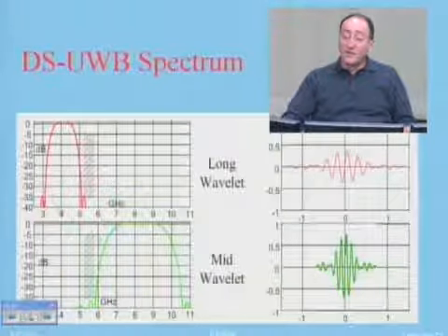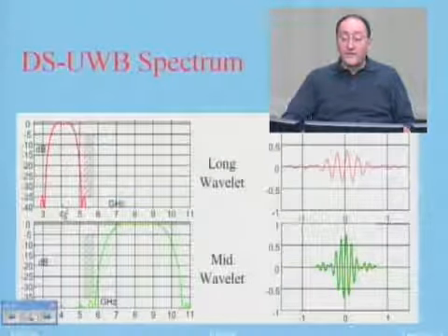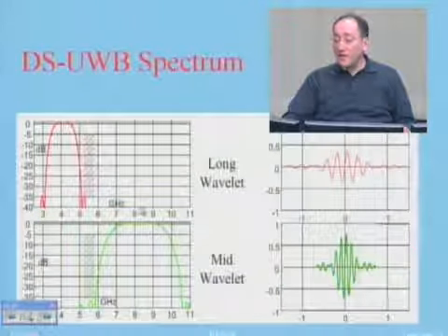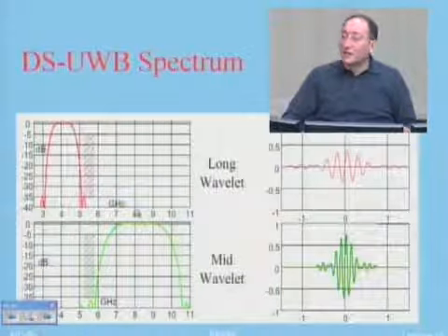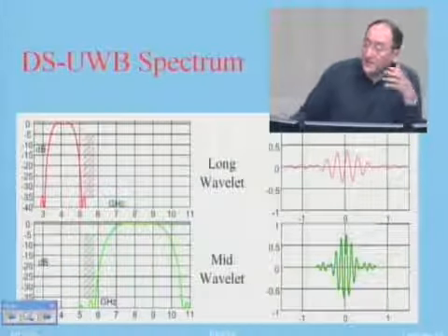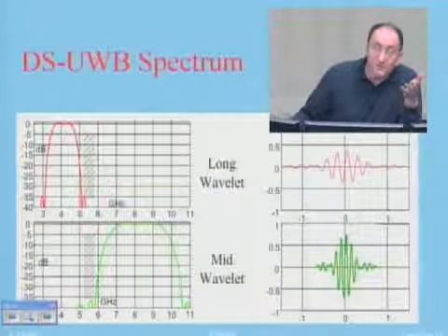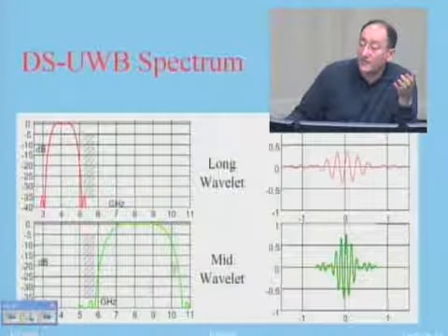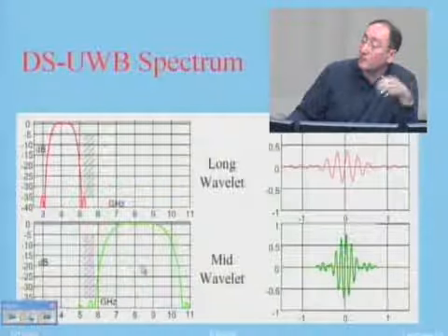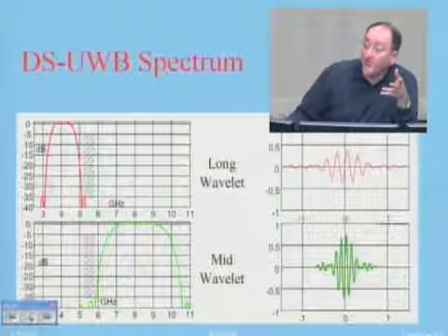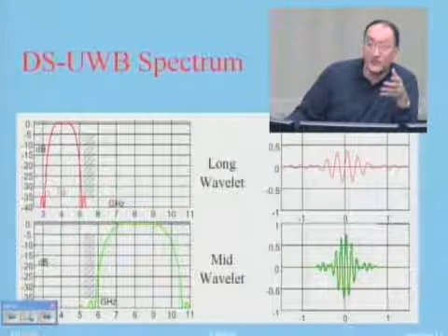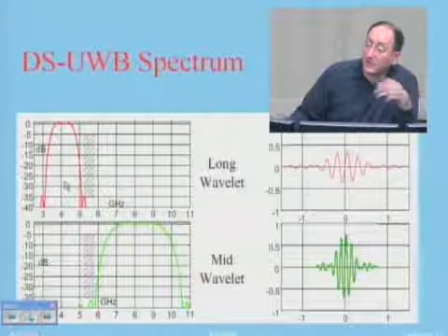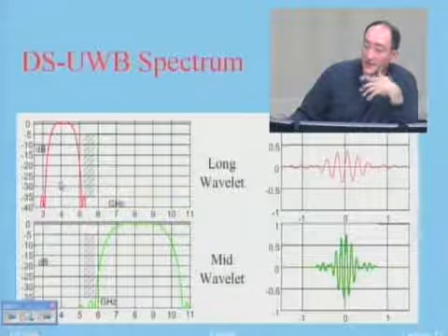Number two is that I have two bands. Why two bands? Well, center frequency in here is 4, center frequency in here is like 8. We remember that if I increase the center frequency, my coverage becomes worse. So if I come to here, I have shorter distance coverage, but I can go to higher data rate. If I come in here, I have longer distance coverage, and I can come to lower data rate. So that's a good solution, very flexible.